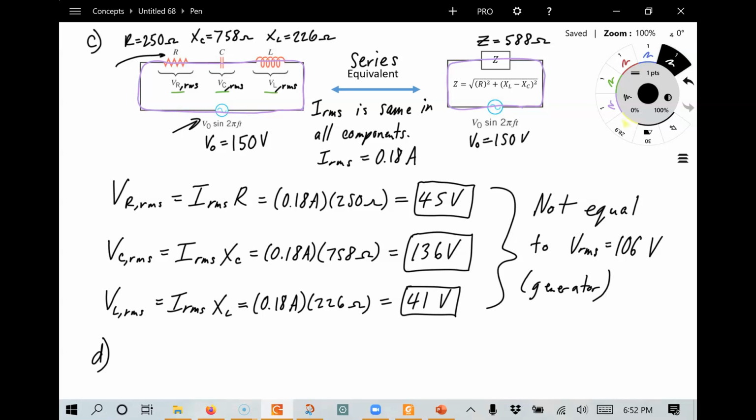In the capacitor and the inductor, something else happens. In the capacitor, as charge builds up on the plates, you generate an electric field, and that stores energy. Later it returns it to the circuit by contributing to the current. But there's no energy lost in the capacitor. For the inductor, similarly, when the current is changing, it generates a magnetic field, and that magnetic field stores energy in the inductor. As that field decreases, it gives energy back to the circuit, but no energy is lost in the inductor either.